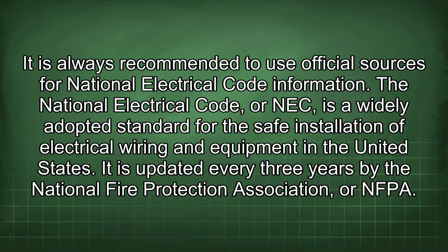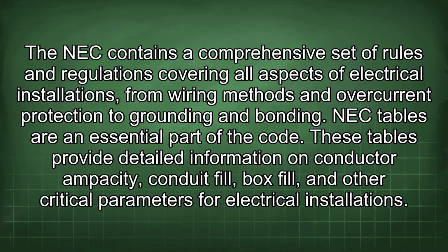The National Electrical Code, or NEC, is a widely adopted standard for the safe installation of electrical wiring and equipment in the United States. It is updated every 3 years by the National Fire Protection Association, or NFPA. The NEC contains a comprehensive set of rules and regulations covering all aspects of electrical installations, from wiring methods and overcurrent protection to grounding and bonding.